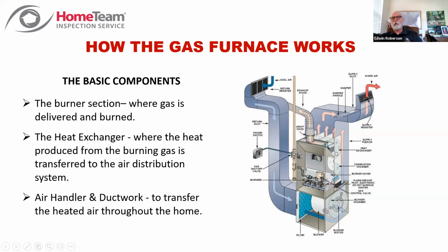Well, in the process, you're heating up this metal of the heat exchanger, and then you're blowing the house air from the air handler that you see at the very bottom. You see how the return duct comes back through, and then you're blowing air across that heat exchanger and then out into the home. So you're drawing heat off of that heat exchanger with the house air and blowing it into the living spaces, and that's the source of your heat.